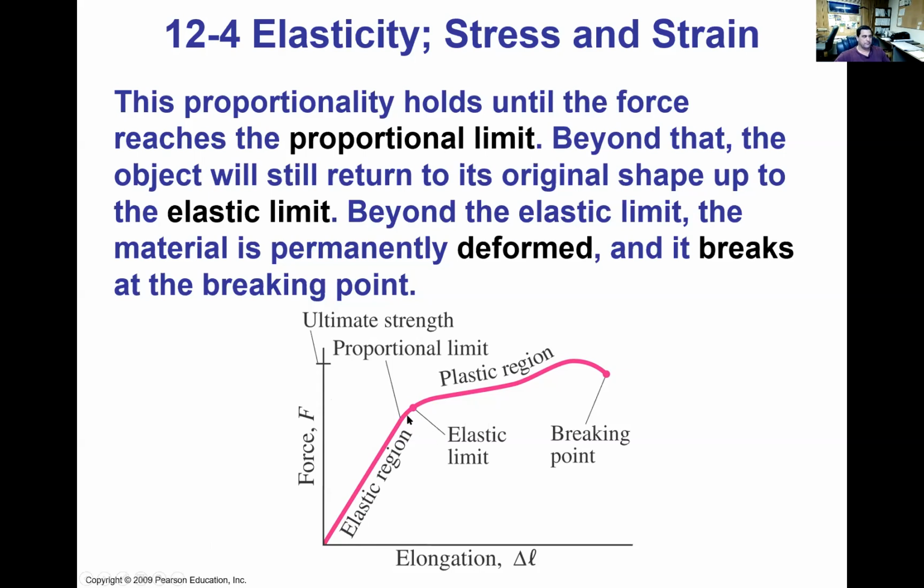Once you reach this proportional limit, you're starting to get to the elastic limit. From that point on, if you apply any more weight or force and you take that force off, it is permanently going to be deformed. And if you keep carrying it into this plastic region, it'll go through a phase called strain hardening, where it reaches the maximum force you can apply, and then there's a slight dip before whatever it is breaks or fractures.